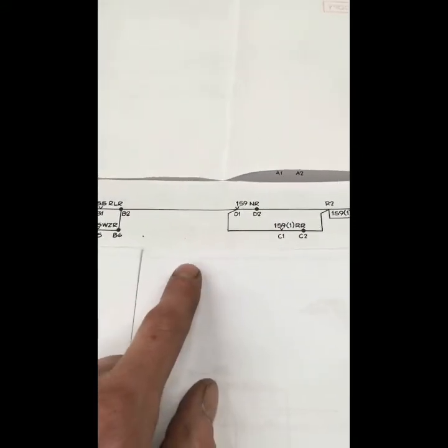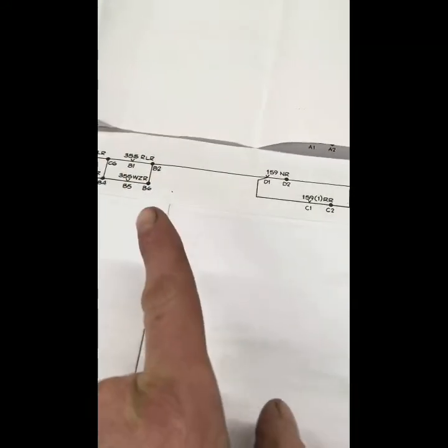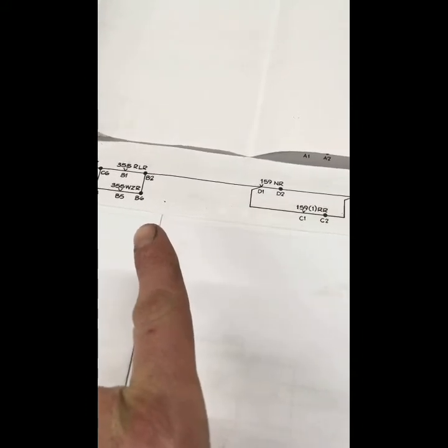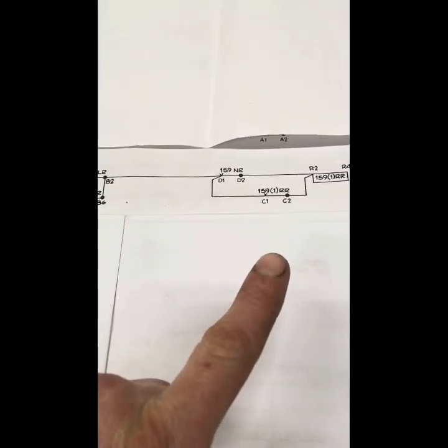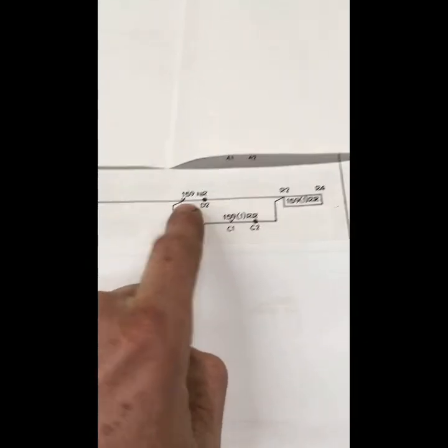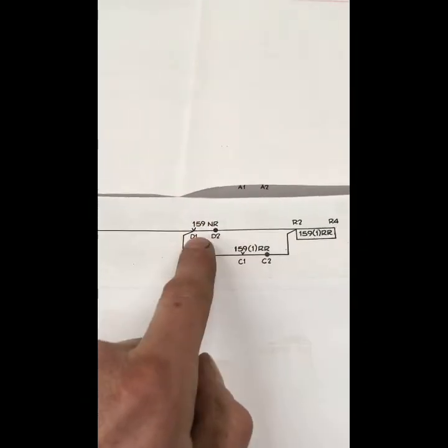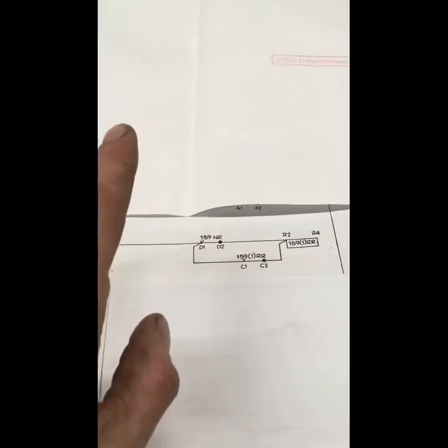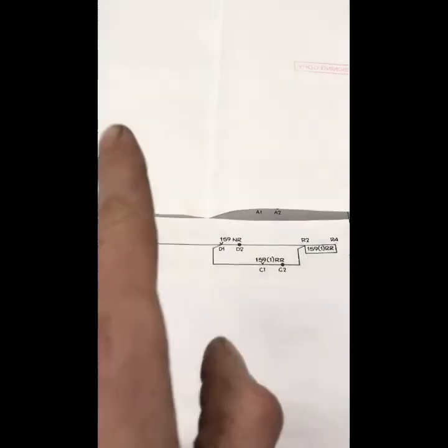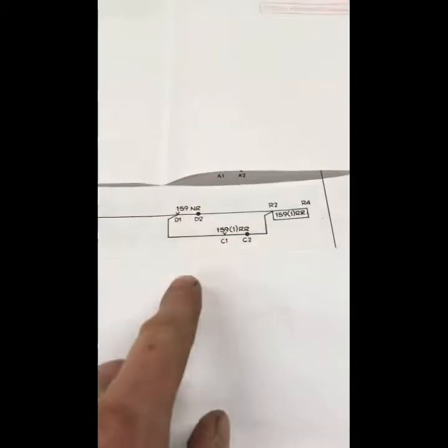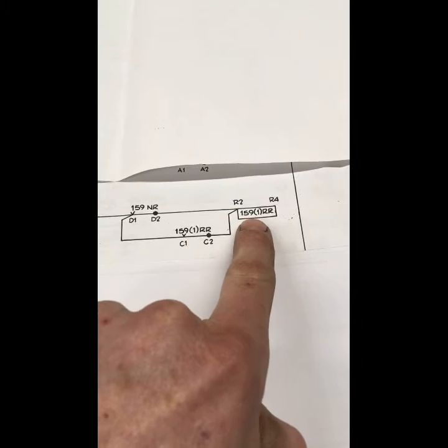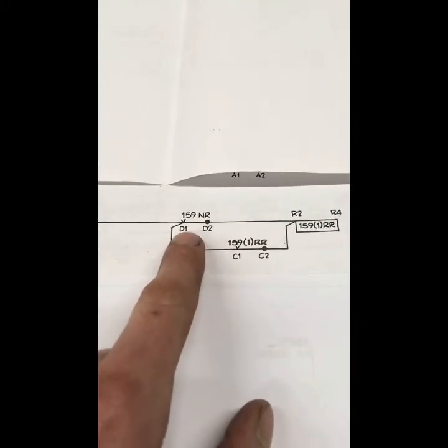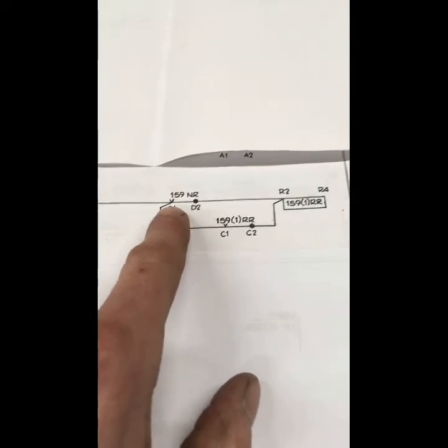Remember I mentioned that, a bit like a lever, the lever is either normal or reverse. If it's at normal, the signal is on at danger. If it is reverse, the signal is cleared at proceed. So here, to be able to proceed the signal, we have to prove it is also not on. What we don't want is a conflict in the relays where we have a normal and a reverse up at the same time, a signal proved on and off at the same time. So to be able to clear our signal, we want to prove that we are not also requesting it to go back to danger. So that will be up to start with.